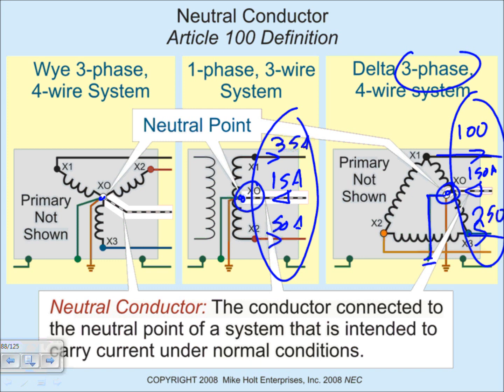Any question about the two systems on the side, guys? Neutral point and neutral conductor, or grounded conductor, a fancy name for neutral conductor. What's the advantage of this? It gives you two levels of voltage. So that's one of the reasons why we have a grounded system, guys. It stabilizes the system is one. The other one is to get two levels of voltages.